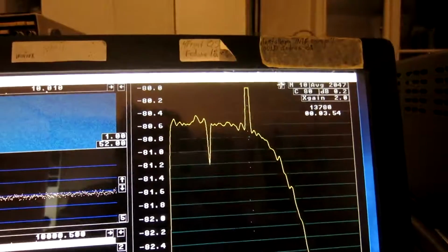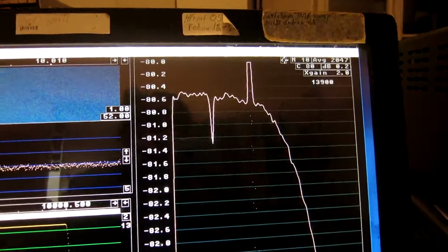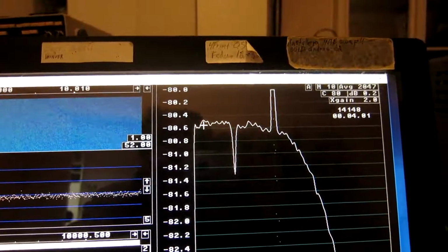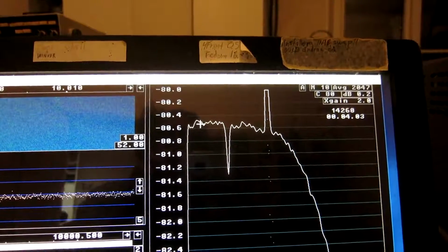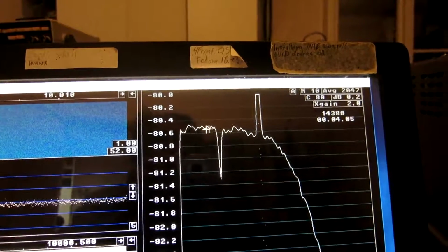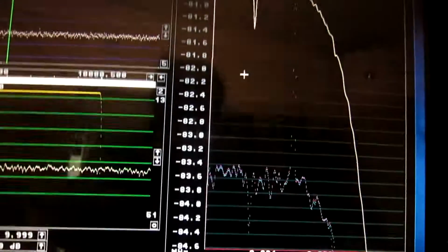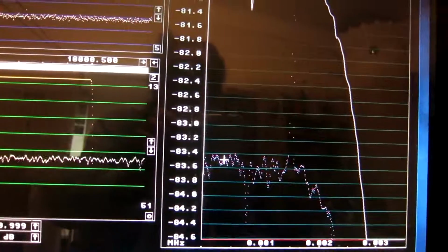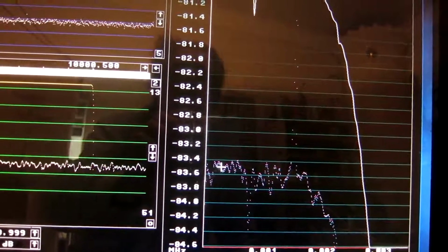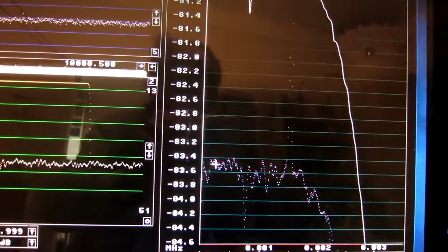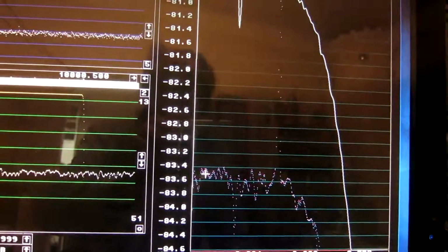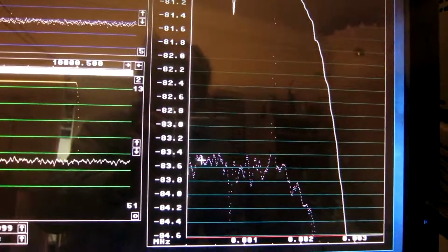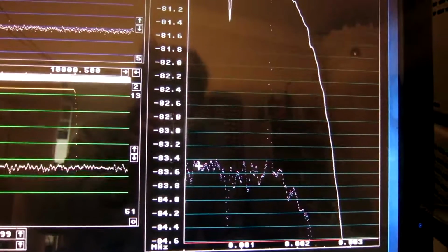And I looked at the amplitude noise, and this is at 80.6, well, minus 80.5. And the same is here for the average power spectrum, but this is at close range. Maybe there is something with some AM noise from the amplifiers.